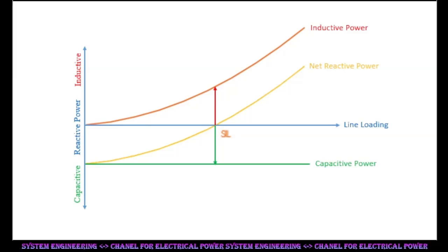The reactive power of the series element varies with the load. A capacitor added in line seems to have a self-regulating feature because the capacitive power of the added element varies with the inductive power of the line at various load conditions. But it can be connected the other way also, as suitable.